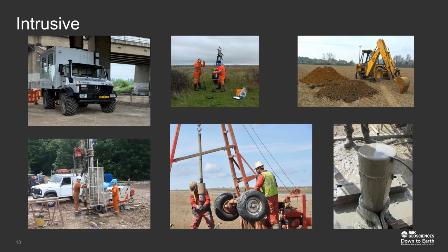Generally, our dynamic sample, so the one in the top middle, is used for investigations up to 5 to 7 meters. But then our cable and our rotary drilling can be used for deeper investigations going up to 100 meters. All of these techniques have different forms of in situ testing. This is conducted directly onto the soil to measure the soil properties. So, for example, standard penetration testing measures the soil resistance to penetration. Cone penetration uses a cone-shaped device to measure the soil resistance and gather data on soil stratigraphy.